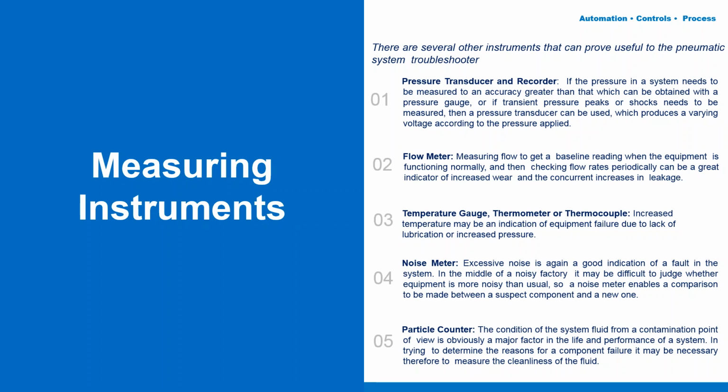Now in pneumatic systems, I don't know too many people who have their own particle counter, but there are any number of laboratories that can take a compressed air sample or have you run some air past a filter for a predetermined amount of time and then send that filter in for analysis to see if contamination of some kind is the cause for repeated failures.